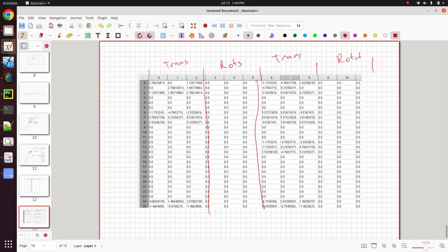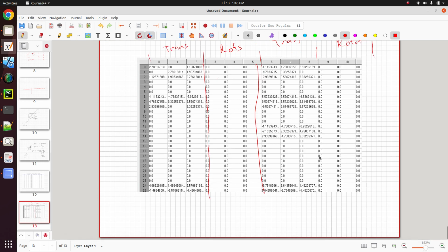So this is bad, because when you try to find k-1, which is going to be equal to the adjoint of k, let me do this at the bottom. So when you try and find the inverse, one way to find the inverse is to do the adjoint of k over the determinant of k. With these 0 columns, you'll notice that the determinant of k is equal to 0. So then this creates an undefined solution of inverse of k.